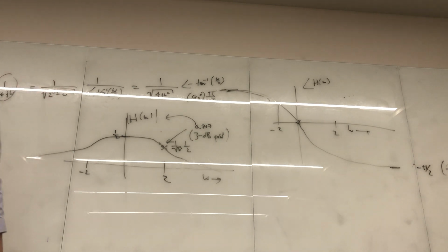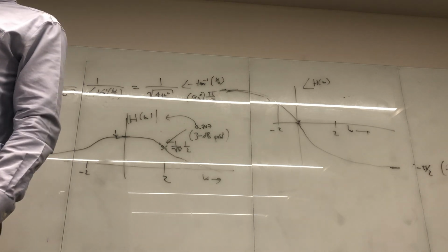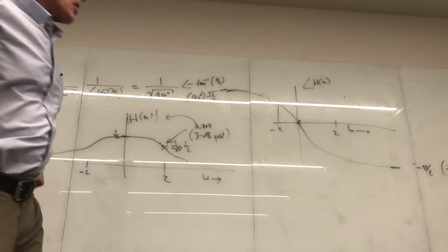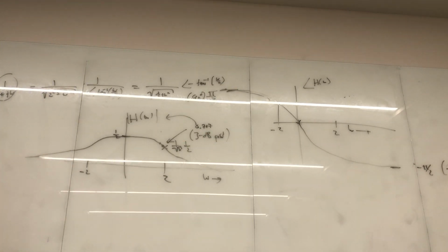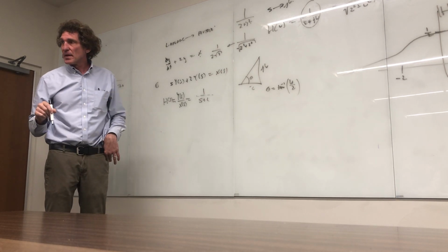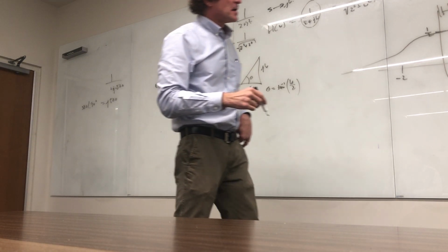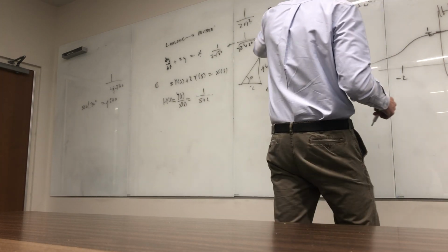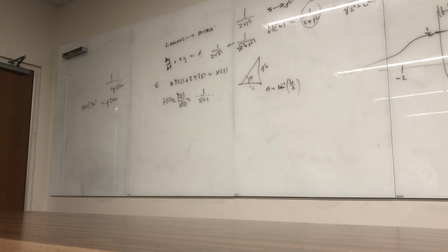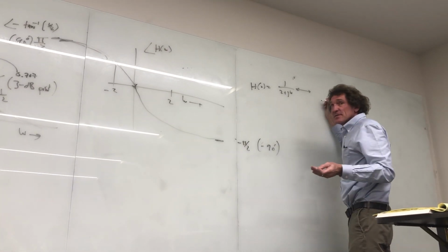Now, the next part of the problem was, I did that. Did they want the impulse response? Let's get it anyway, if they didn't. All right, if I have this differential equation and I want the impulse response, it means x of t becomes delta of t, correct, class? Since I have H of omega equal to simply 1 over 2 plus j omega, when I go back to the other domain, this is the simplest one of all.